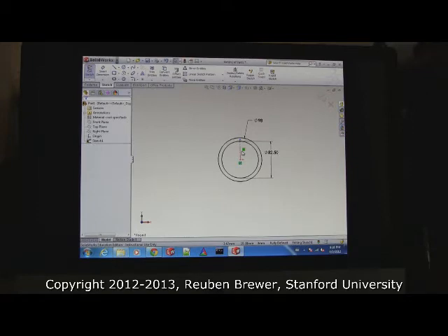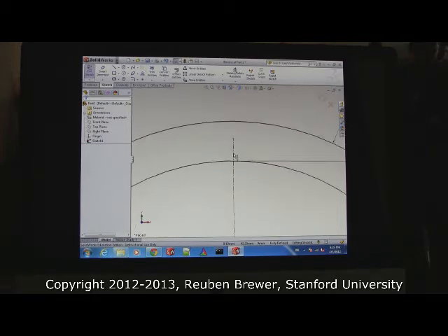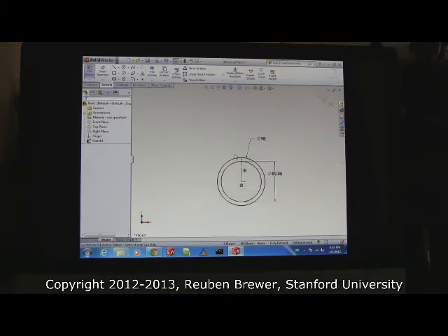That is because you're too zoomed out. So delete the line. Now I'm going to show you one of the reasons why you have to have a 3-button mouse. This is really small, I can't see it, right? Everybody look at my screen for a sec. Oftentimes you get into this weird thing in SolidWorks where it's decided that you have terrific vision. So scroll your middle wheel, and we zoom in. Everybody see that? You don't have to press anything on your keyboard, just scroll in.